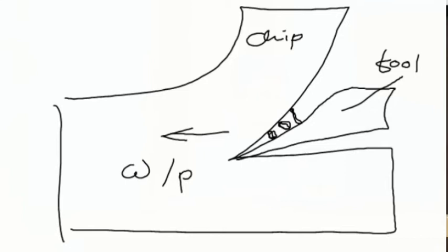So whenever these welds break, there may be chances that some of the particles from this rake surface of the tool get detached and flow away with the chip, causing failure of the tool.